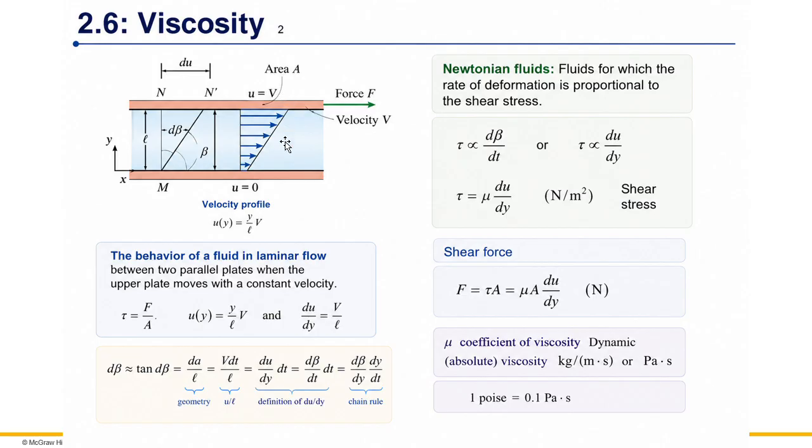And we will introduce the no slip condition, which means the fluid next to the wall will not be moving, but it will be attached to the wall. So in that case, the fluid layer at the bottommost plate will remain as it is, and the fluid layer near the top wall will move along with it. So the velocity profile of that is as shown here. If you are looking at the fluid on the top, it has higher velocity, and as you go down, the velocity is smaller.